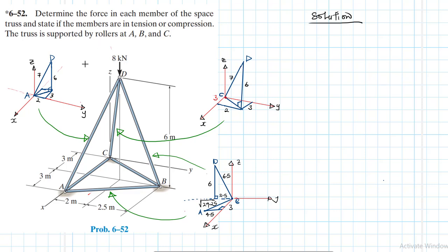So what we need to do now is draw the free body diagram quickly, which we did already in the other case. We have reaction forces here. We have BZ there, we have AZ, and then there we have CZ. Let's imagine we are having compressive forces at that joint, so all the arrows will be pointing up like that.